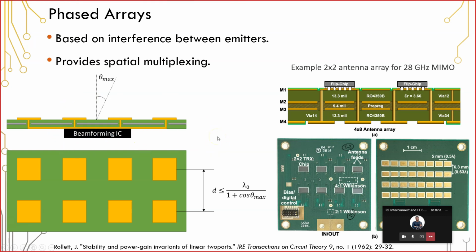So beamforming works in reverse, and it works on the receiver. Using that phase difference between these two waves, you can then figure out the angle at which those waves arrived. That's a pretty simple calculation. So it works in both ways: you can transmit at a specific angle, or if you want, you can detect the angle that your antenna array received at.